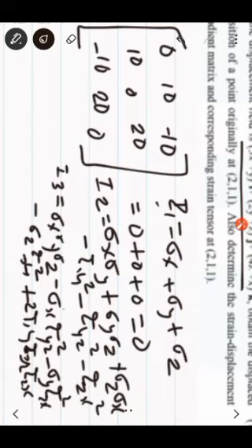Then you have minus, taking three at a time: sigma x is there, so tau yz square; minus sigma y is there, so tau zx square; minus sigma z is there, so tau xy square; then plus 2 times tau xy tau yz tau zx. So I have three things, I1, I2, I3.